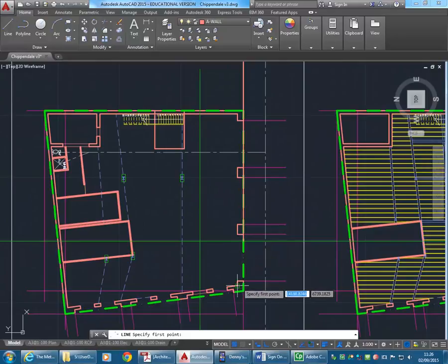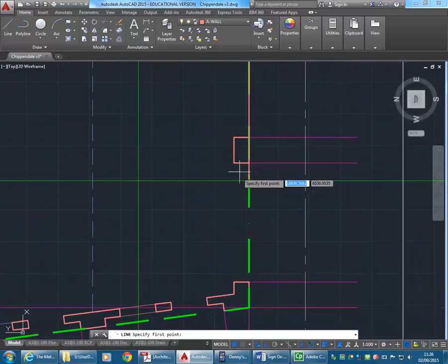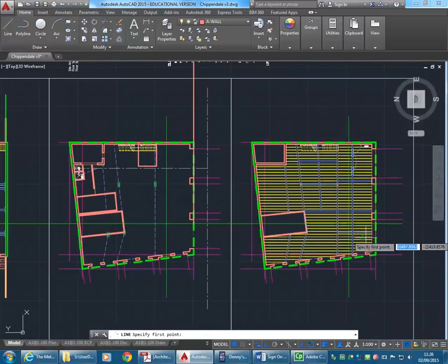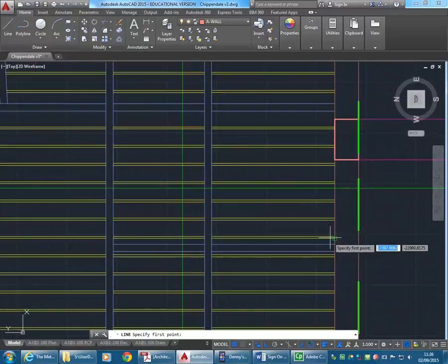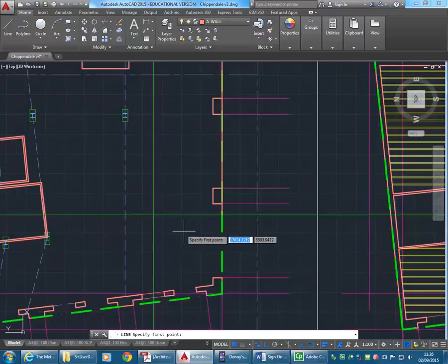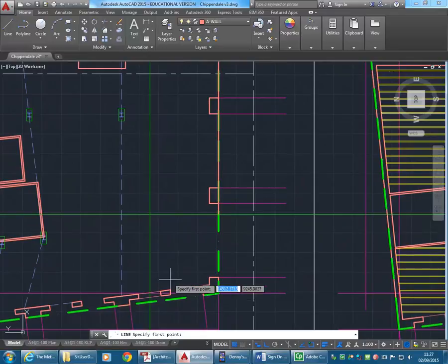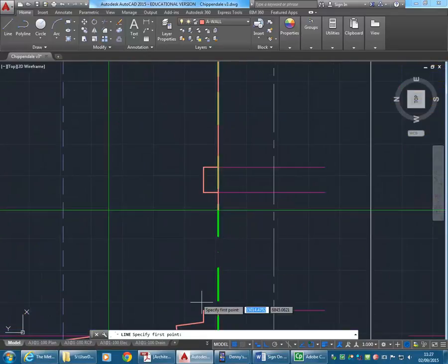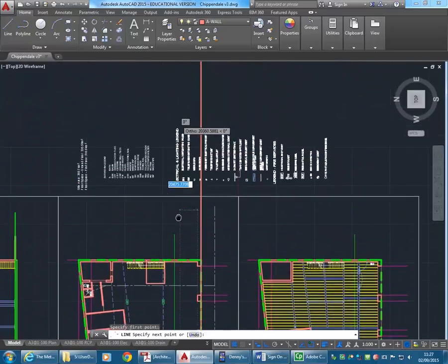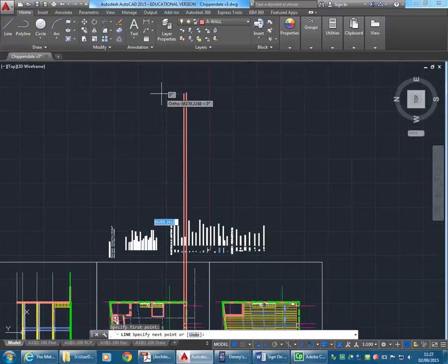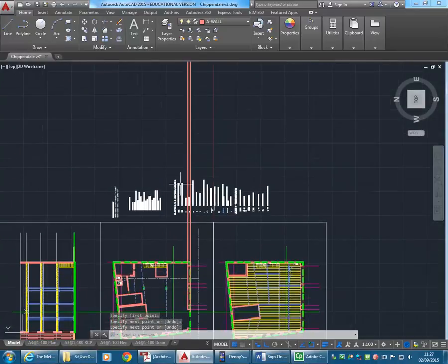And here you'd need to use a bit of judgment to work out where the wall above this is. You can see it there. Well, again, if you ever look in your photos, you might work out that it's actually concrete above these, and it does get narrower, but for now I'm just going to project from the inside face of the wall and draw the thick part of it coming straight up. So that's my wall thickness on one side of the building.